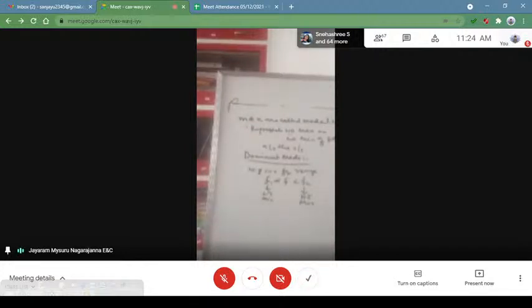Similarly, for 10 gigahertz and 30 gigahertz, 10 gigahertz will be the least frequency, which corresponds to the longest wavelength. So the lower threshold of the frequencies is generally considered the dominant mode frequency of the waveguide system.